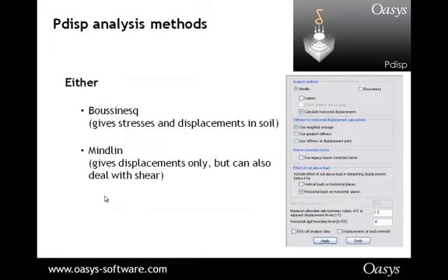And if we look at the analysis methodology for Pdisp, Pdisp uses the Boussinesq method, which gives us stresses and displacements in soil. And it gives us the Mindlin method, which gives displacements only, but can also deal with shear.